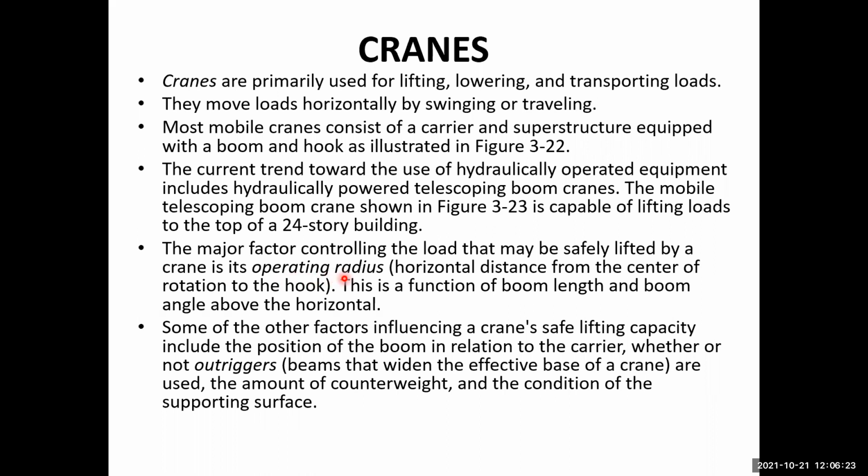If the operating radius of the crane will be more, there will be more overturning moment on the crane. So if there will be more overturning moment on the crane, that means the load carried by the crane should be less. So the proper control of the weight which the crane is carrying is important for the operational safety in the crane.